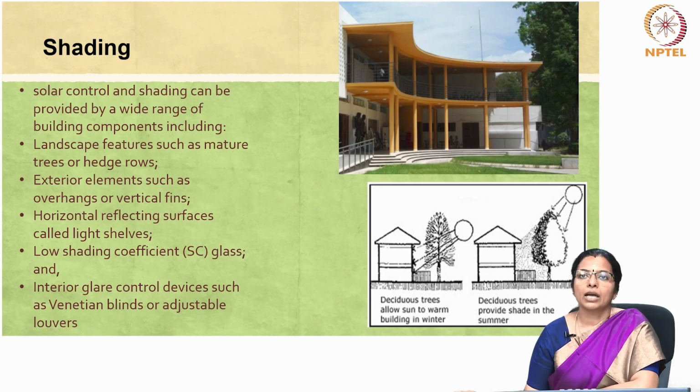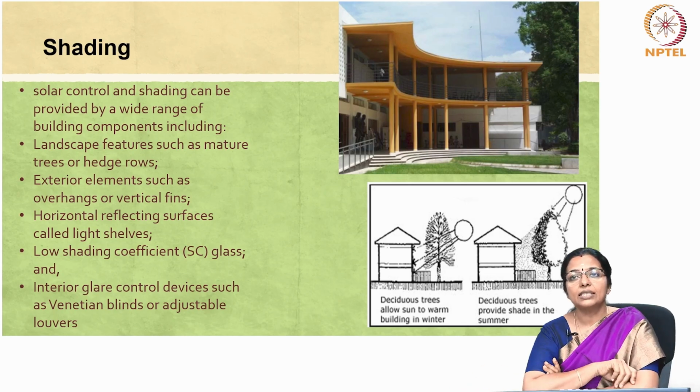The orientation of building openings significantly influences the design of external shading devices, with solar radiation incident being a key consideration. Seasonal variations in the sun path are directly linked to orientation, impacting the angle of solar radiation. During winter in the northern hemisphere, the sun path is low and slightly south of east and west. In contrast, summer sees a higher sun path north of east and west.